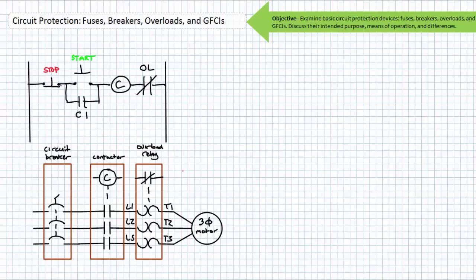The contactor closes when some other circuit tells it to. This is the really neat part. The control circuit could be low voltage, low current, and totally electrically isolated from the high voltage, high current motor supply circuit. It's like two totally independent circuits that only interact with each other at certain points, one of them being the contactor, the other point of interaction being the overload.